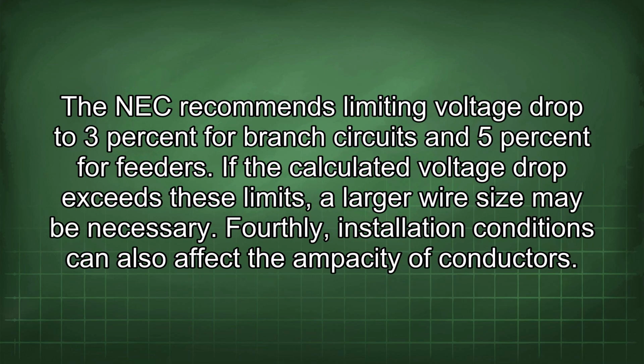Thirdly, voltage drop should also be considered to ensure that equipment operates properly and efficiently. The NEC recommends limiting voltage drop to 3% for branch circuits and 5% for feeders. If the calculated voltage drop exceeds these limits, a larger wire size may be necessary.